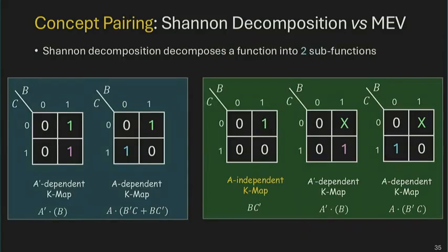So if you put them side by side, and you compare this expression versus the expression on the right by adding together these 3 implicants, you will see that this one has 2 variable implicant, 2 variable implicant, 3 variable implicant. Over here, you have a 2 variable implicant, 3 variable implicant when you apply distributivity, and another 3 variable implicant. And if you treat that as a logic minimization result, this one is not optimal. That one is optimal.